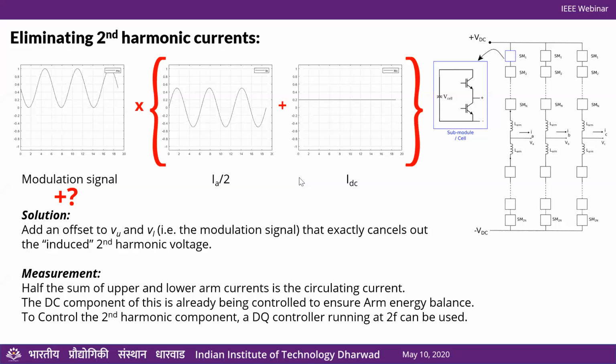That tells you how much current is flowing through the module, and that tells you the capacitor value. However, there are other considerations like life, temperature, loss, and all those things. So I have a feeling that industrial designs would consider all of these things and not just the electrical requirement, which is, let's say, 5% ripple in the capacitor voltage.